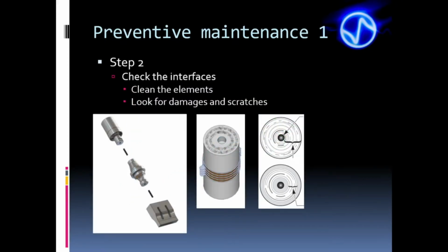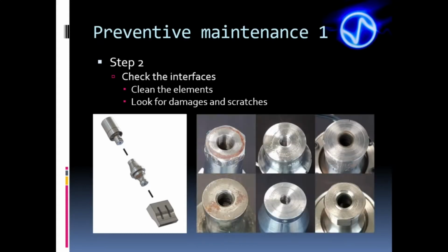We must clean its interfaces with a clean paper towel or cloth and solvent to remove all dirt and grease. We also need to clean the studs with a brush or ultrasonic cleaner. We then inspect the interfaces of the elements of the stack, checking them for wear and grooves. This wear is normal and occurs simply by using the stack.